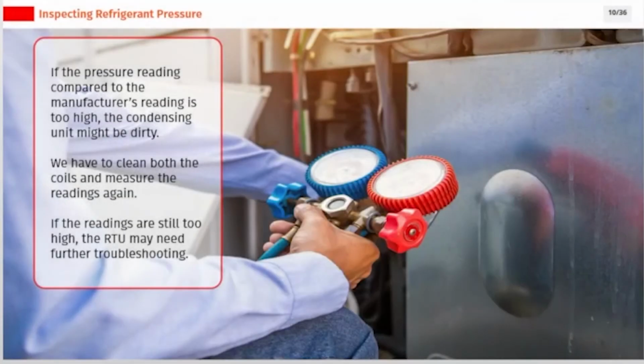If the pressure reading compared to the manufacturer's reading is too high, the condensing unit might be dirty. We have to clean both the coils and measure the readings again. If the readings are still too high, the RTU may need further troubleshooting.